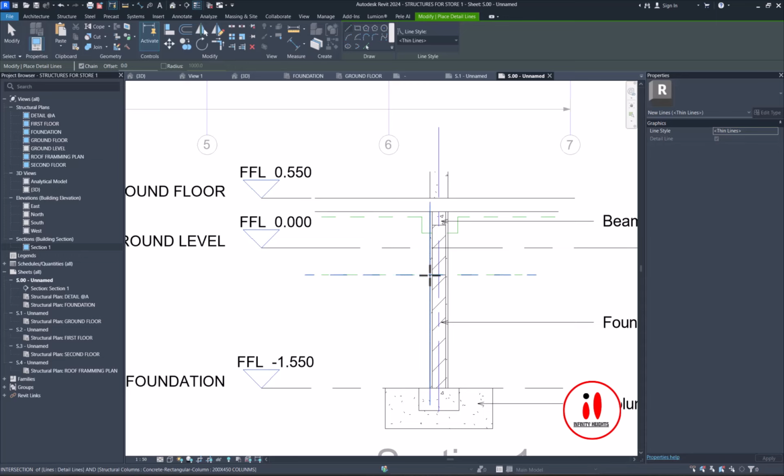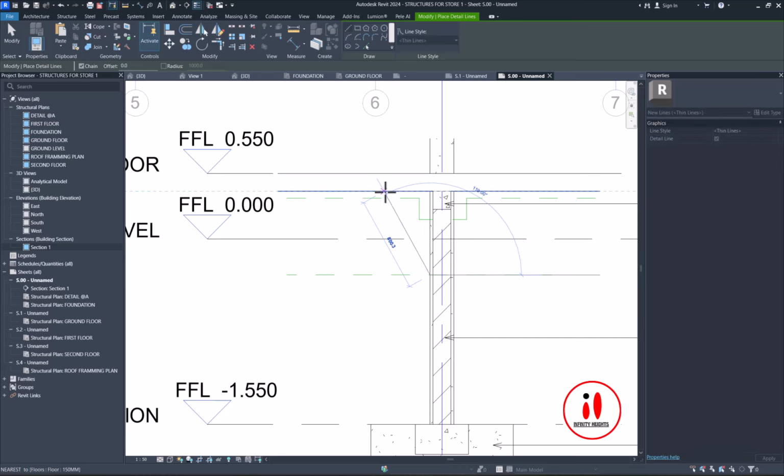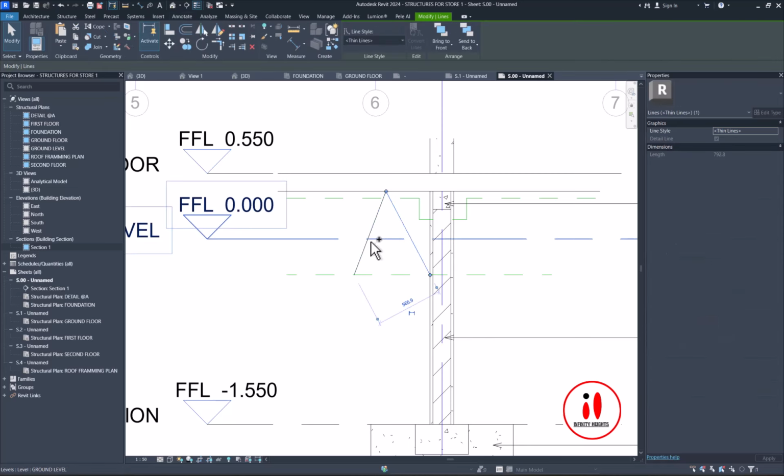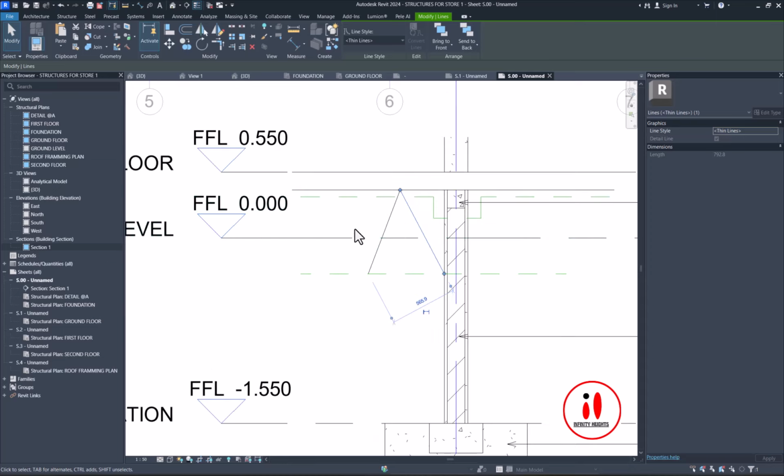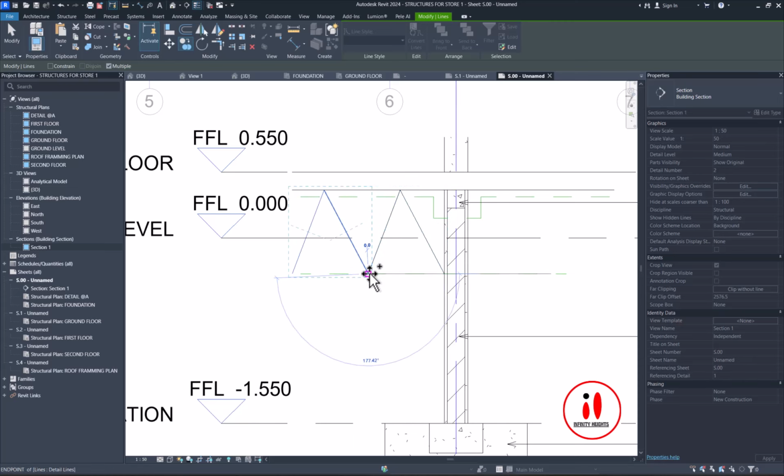You get it. So now we are going to have our hardcore filling somewhere from here. On this side they are going to excavate all here for the bases, but on the other side they just cut the topsoil. So after the topsoil, all here is going to be void because you have a slab depth of 600 or 550. So they have to fill. You get it. So you provide a callout. You can do the 150 or 300, depending on the size. So we have the callout here. You can copy it like this.